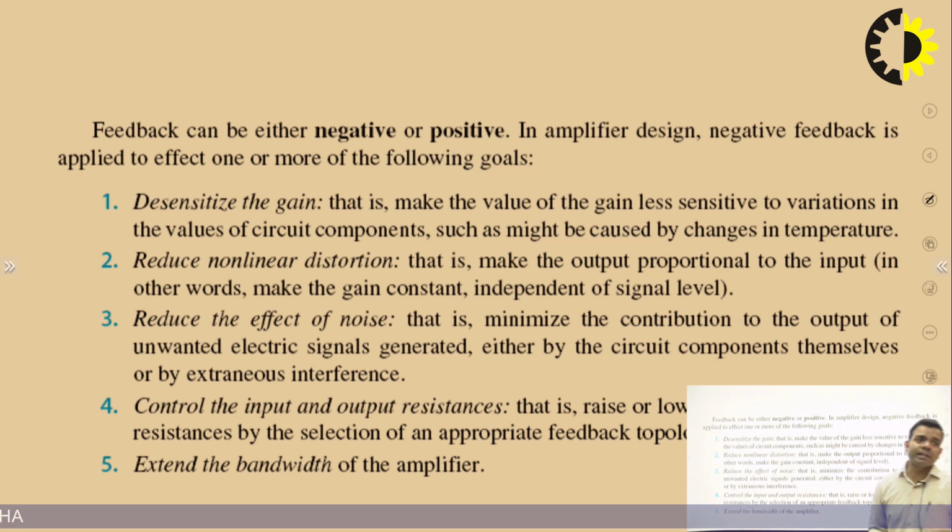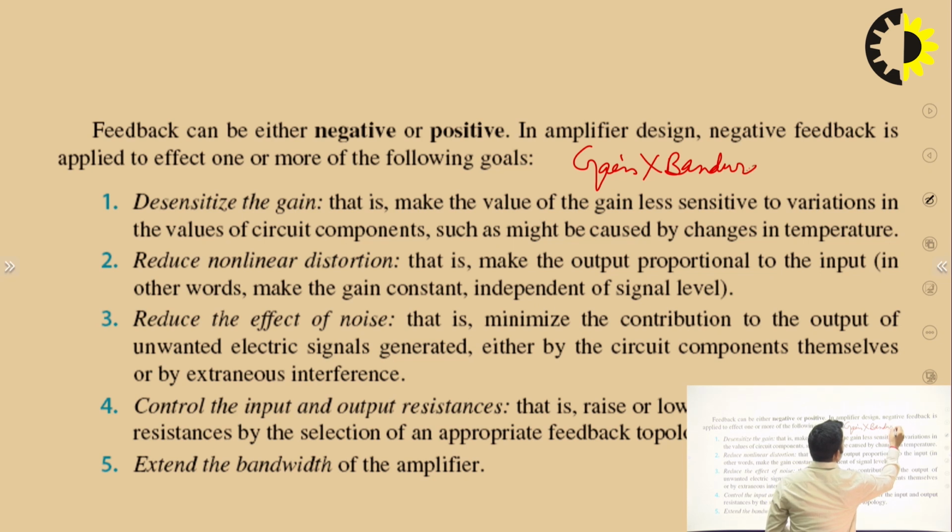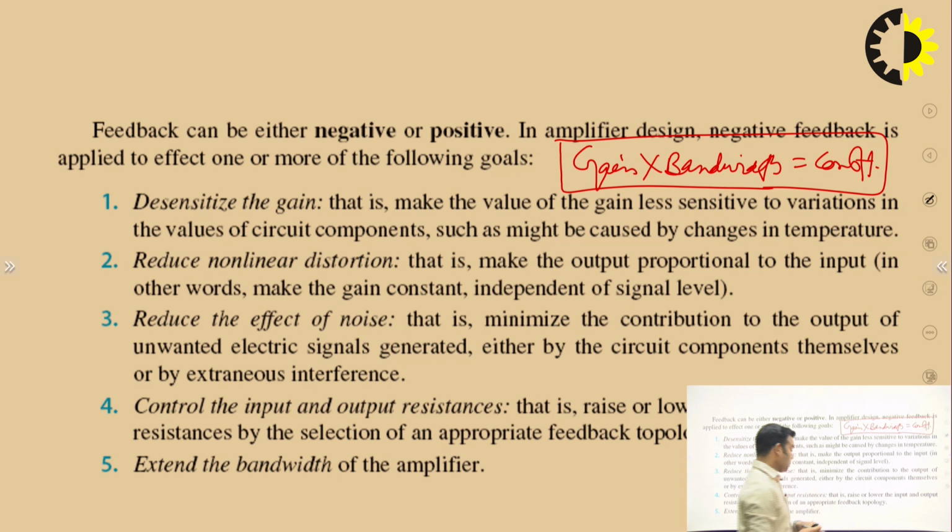Another advantage is extend the bandwidth of amplifier. This is also one significant advantage of negative feedback. And you can remember it very easily that gain and bandwidth product is constant for any amplifier, and we have seen earlier that gain decreases in case of negative feedback. So whenever gain will decrease, obviously bandwidth will increase.